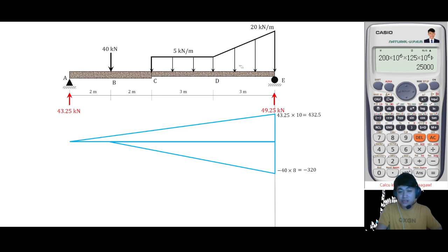Okay, 40 times. And then we have a rectangular load. Let's just make it a rectangular load on this entire length. So just get the moment of this 5 kilonewton per meter to your point E. It will give us what type of moment diagram by parts? Obviously, that is a spandrel, second degree.